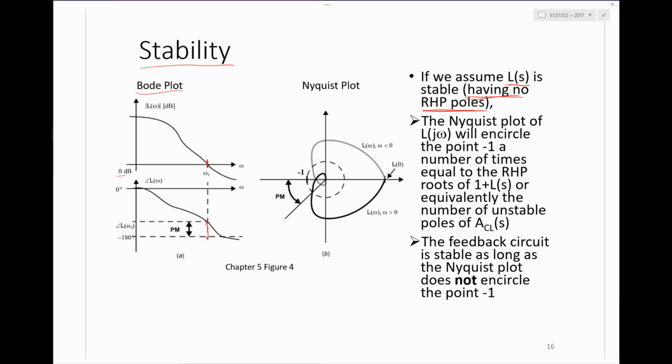If that's ever not the case, then all the stuff we're talking about is kind of off the table. But for all the stuff we're going to talk about, we've got amplifiers with high gain at DC and then one or two poles, and the gain starts rolling off. And so L is clearly stable on its own. It's only when we put it in feedback that we can get into trouble.